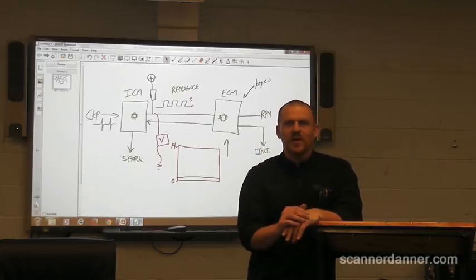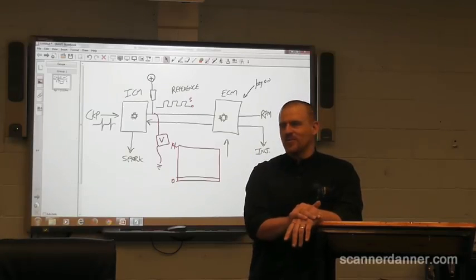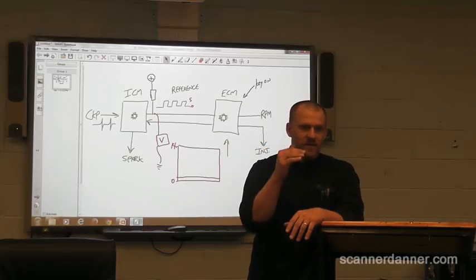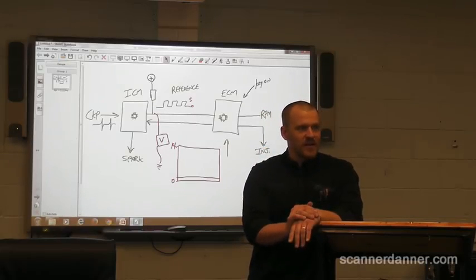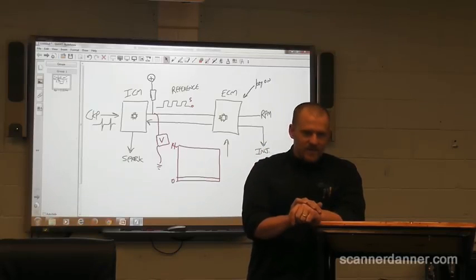Put another module in it. You got a bad module out of the box. I've seen that happen, a bad ignition module right out of the box. It's not common, but it does happen. So I told him to put another module in it. He calls me back later in the day. The truck's still not running. I got to go back.